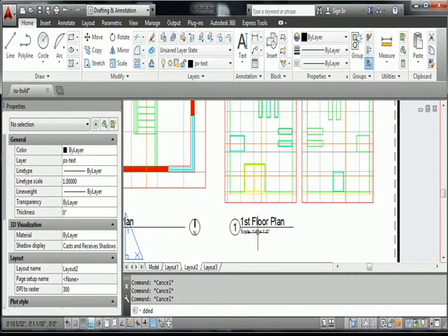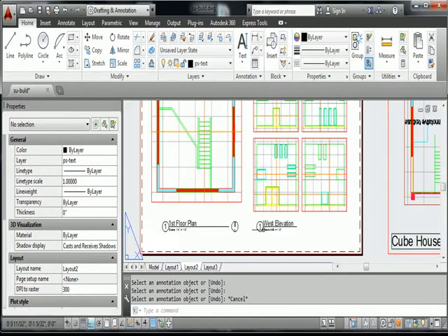Then I can say dd edit, and the elevations, if I recall, were 1/8 inch, right? 1/8 inch scale, so I'll change the ID to 1/8 inch scale. Whoops. And then it's not a floor plan anymore. This one will be a, what was it? East, north, west elevation. So west elevation. Okay, and I could indicate these guys as well.